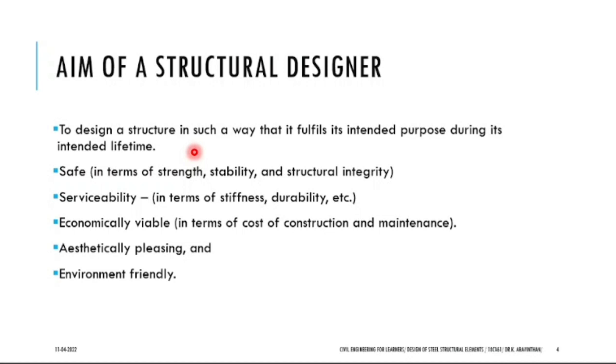As far as AICTE is concerned, they give 102 meter square as the classroom size. If you want to construct a college, it should have a minimum classroom size of 102 meter square. You cannot take the 102 meter square straight away. Why? Because it might be a technical drawing class. Since you are an engineering student, you know you have technical drawing, yes or no? The technical drawing class is different from a normal classroom. It needs 150 meter square of area. So AICTE will give you the minimum, that is the border line, and you have to take and decide the judicious dimension.